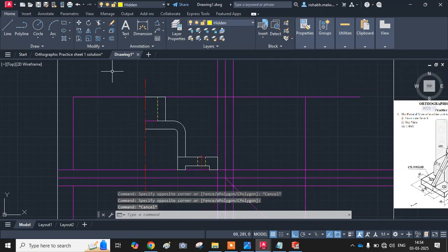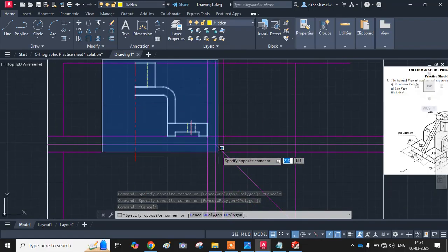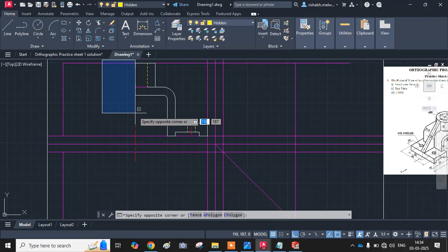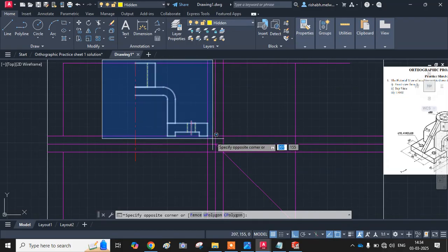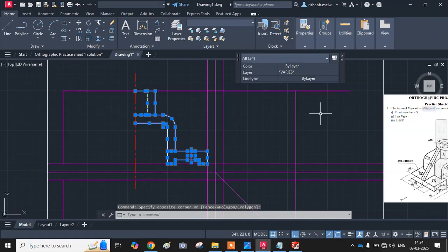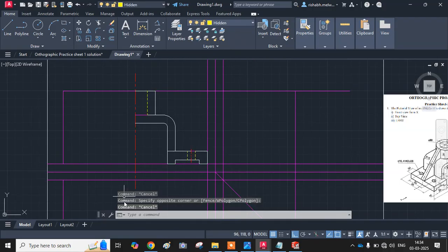So if I click here and if I select carefully this much, सेंटर लाइन नहीं चाहिए ना मेरे को, ये बीच वाला center line mirror नहीं करना है, तो मैं इतना ही select करूंगा. देखो दिख रहा है ना कितना select हो रहा है. I have selected this. Okay, then I will type, either you can type MI enter before, or you can select and after that also you can type MI enter. Okay, तो जैसे normally करते हैं वैसे ही करेंगे हम लोग.